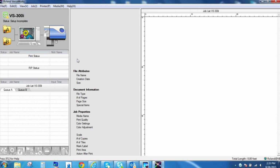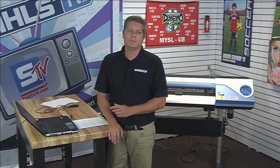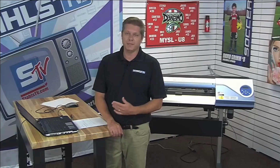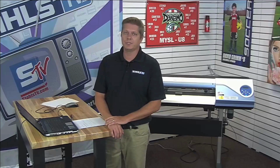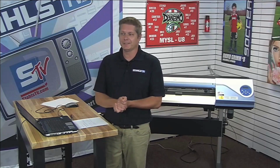Being a former technician, I've come across a lot of customers that were using just the generic vinyl profile, the very first one, the media type. They would never change that under the quality tab. So it's pretty important to use the correct profile and the correct heater temperature settings for each media, so that way you get the best results. So any questions?